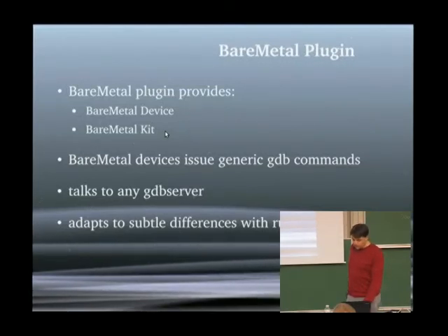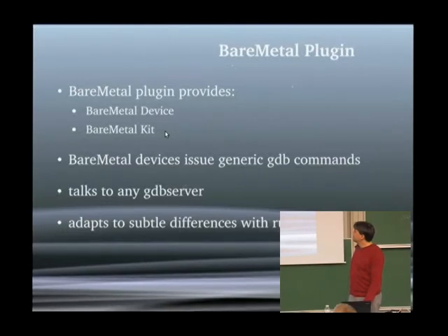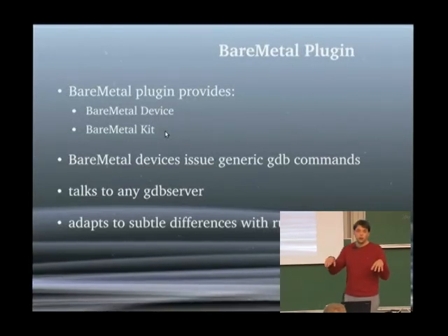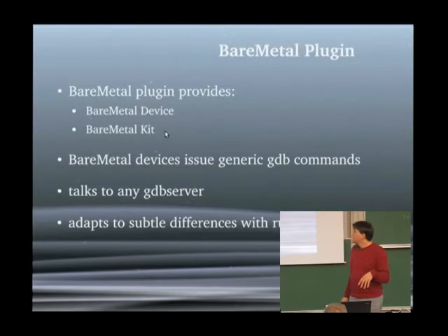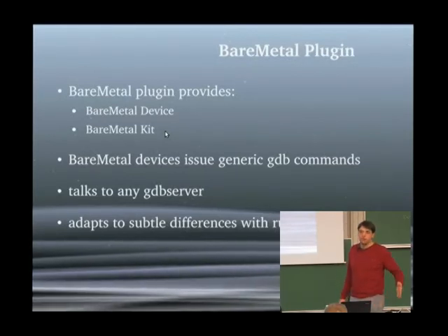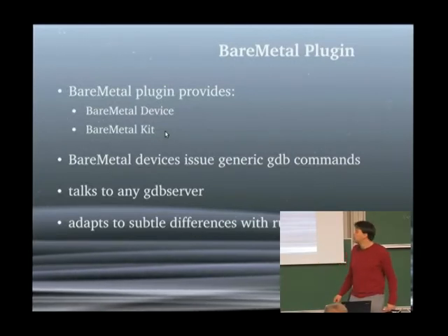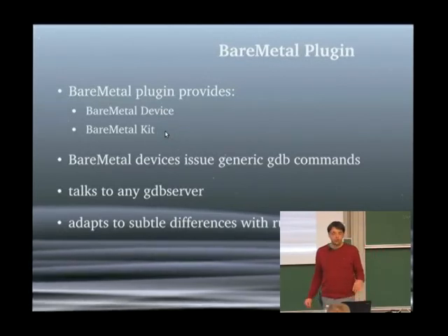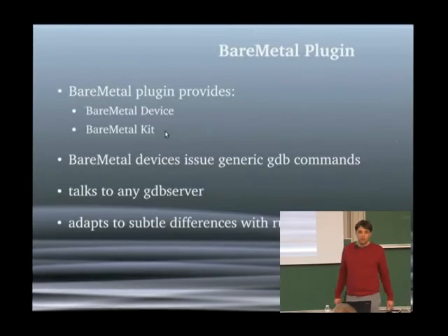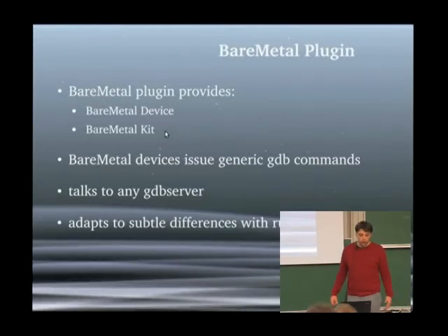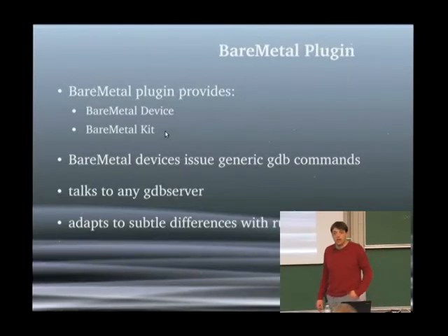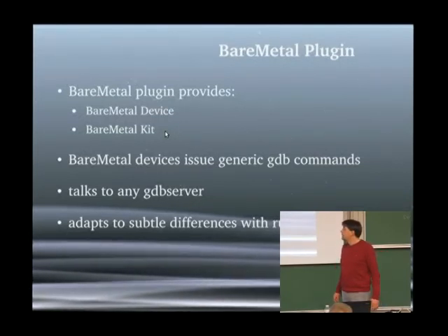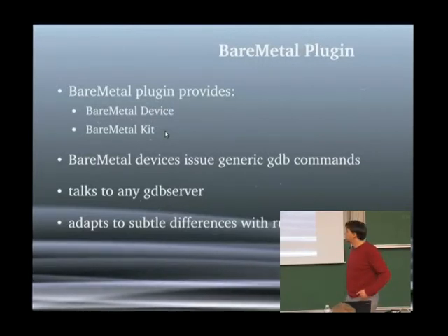BareMetal itself is pretty basic right now, so mainly you can just select the network port and the IP address where the GDB server is listening, so you don't have to have it on the same host. You can just have it running anywhere over the network. And it has a window where you can type in your GDB commands, which is pretty basic but very versatile, because every hardware debugger I used, besides OpenOCD, which are commercial ones, is also able to be used with this BareMetal plugin.